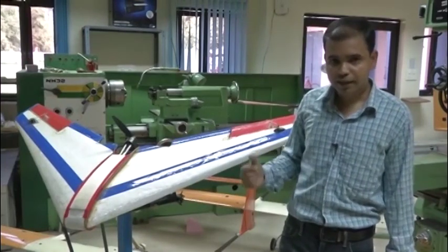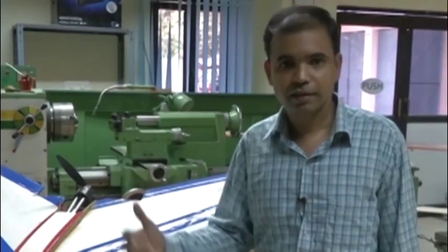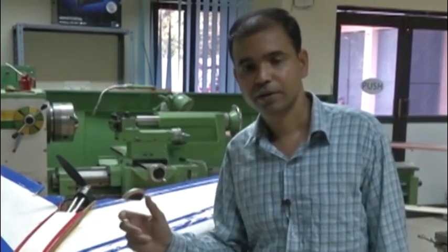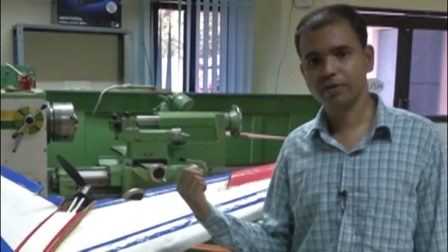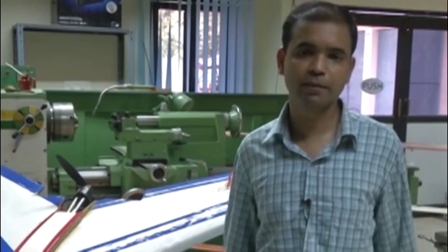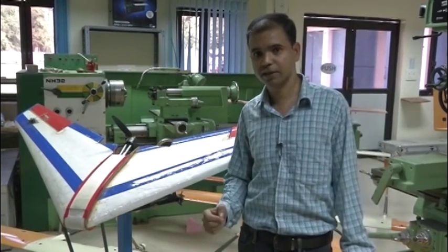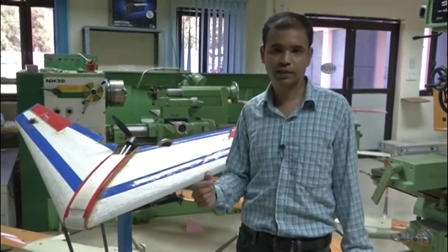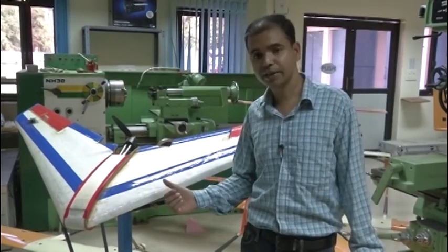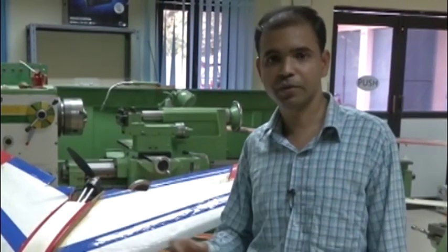In cambered airfoil, we have negative Cm naught. If you remember, in conventional design, we have negative Cm naught because of the wing, but we have horizontal stabilizer. It contributes a large amount of positive Cm naught, and as a result for the whole aircraft we have positive Cm naught. But here we don't have horizontal stabilizer, so we need to ensure something in this design itself so that we have positive Cm naught to trim at positive angle of attack, and that's why in flying wing we use reflexed airfoil. In reflexed airfoil we have positive Cm naught.